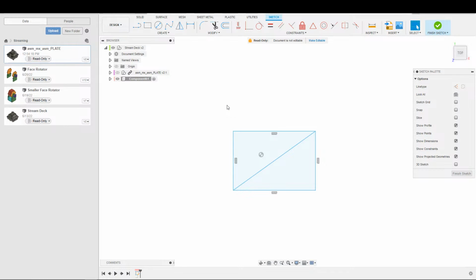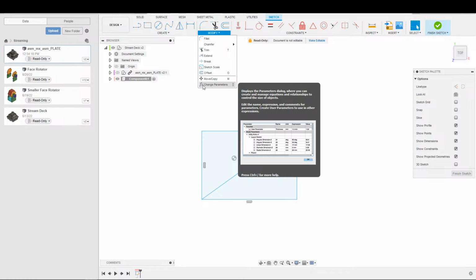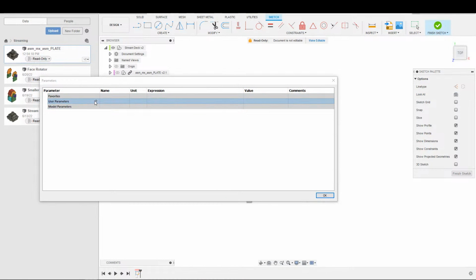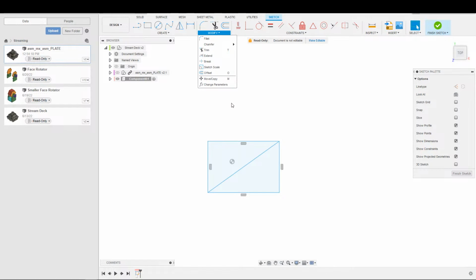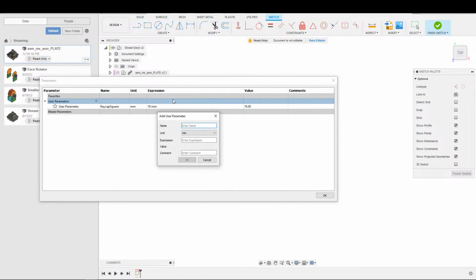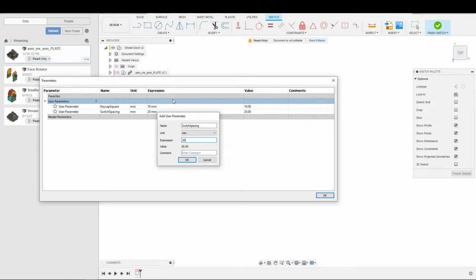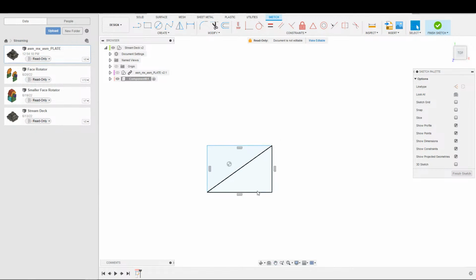So if I cut the keycaps down to 18 by 18, that's probably reasonable. And then we'd have a 4 millimeter space between them, which is probably a little bit overkill. So maybe we do 19 by 19. Okay, so I think that's the plan. I think 19 by 19 is our plan for the keycaps. So let's go ahead and take that down. Keycap square is 19. And actually I should also do the switch spacing. I was saying was 20. Okay, cool.